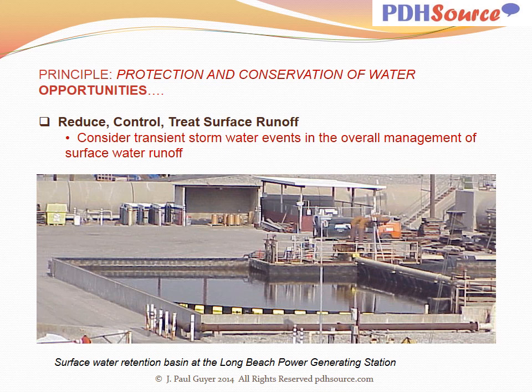This can be particularly important if the surrounding community has a combined stormwater and wastewater collection system that channels all of the stormwater as well as the wastewater into the wastewater treatment plant, because big surges when it rains create operational problems for the wastewater treatment plant. So it may be necessary and appropriate and a good idea to go to the expense of designing in a stormwater retention feature like this.